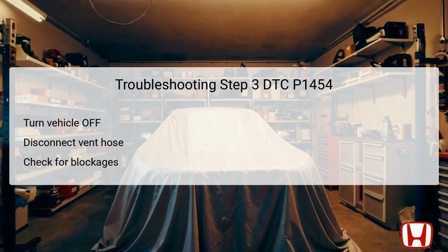Hence, thorough inspection is necessary. Therefore, verifying these vent pathways is essential, as any restriction can directly impact fuel vapor management and lead to further emission issues. Step 4 involves checking the operation of the EVAP canister vent shut valve itself.